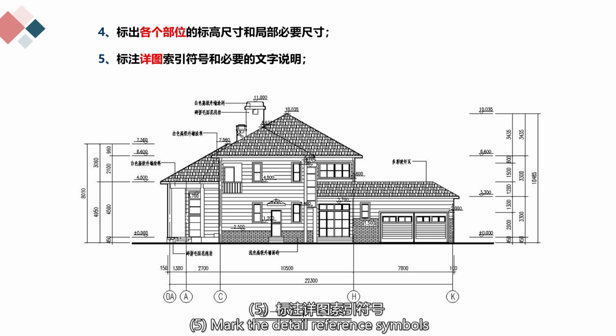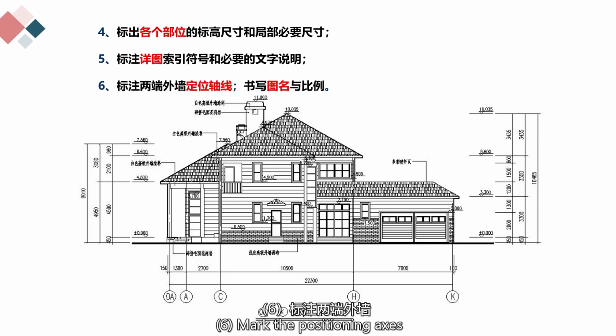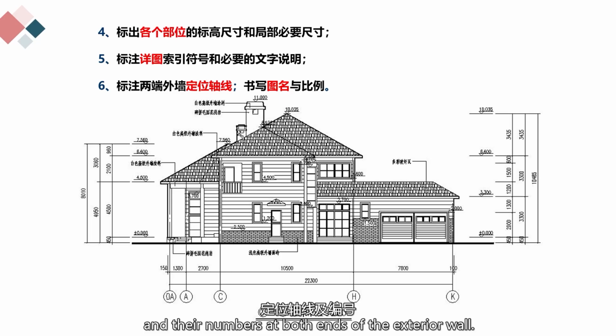5. Mark the detail reference symbols and necessary text descriptions. 6. Mark the positioning axes and their numbers at both ends of the exterior wall. Write the drawing name and scale.